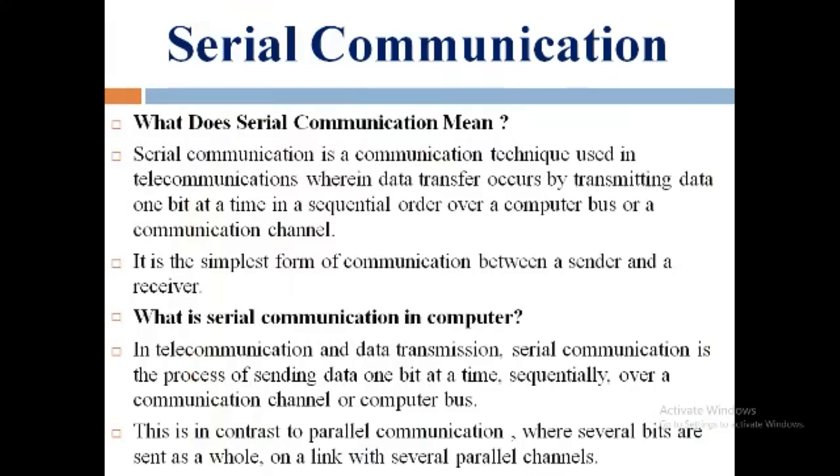First is, what does serial communication mean? Serial communication is a communication technique used in telecommunications wherein data transfer occurs by transmitting data one bit at a time in a sequential order over a computer bus or a communication channel. It is the simplest form of communication between a sender and a receiver.